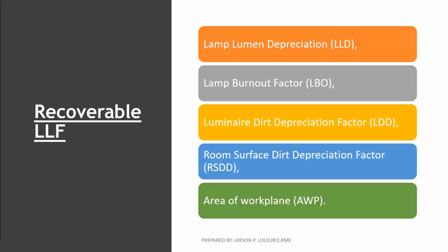So, Illuminance will be greatest near the center of the room. Why? Because kung asa to gi-install ang suga, dito man na nagtapok tanan ang light rays. So, that is why ang center dyan ang pinakayag. And slightly less toward the walls for a given uniform layout of luminaires. Okay? So, kadaganan, walls, muna siya ang uban, ginadungagan na lang siya og mga indirect lighting siya like strip lights para madugangan pud ang kahayag. If you need to put some tables or work planes beside the wall.